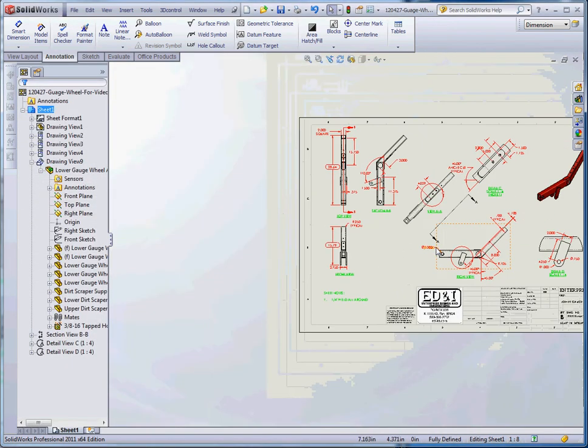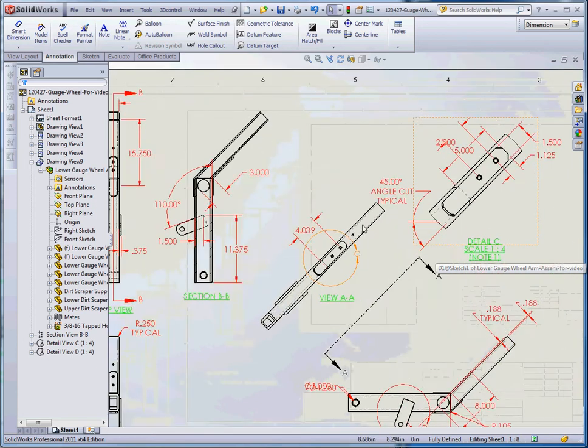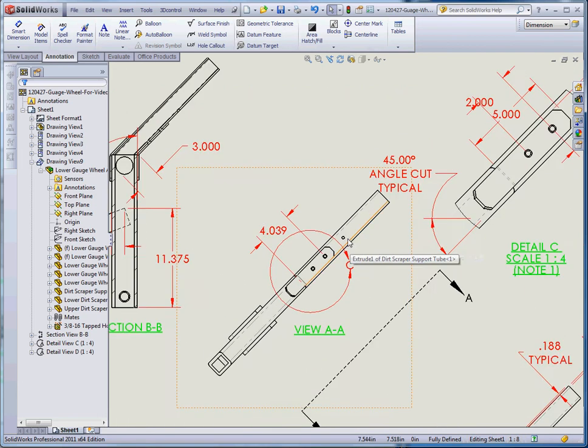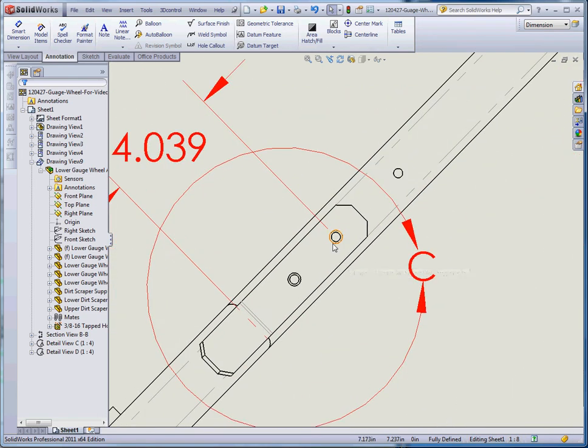And we'll go from there. Alright, so that's our height, length, and depth. Hole callout. It's difficult to get hole callouts on an assembly level. I'm sorry, let me back up. It's hard to get hole callouts on the assembly level when it's on the part level, but if you put a hole wizard location in on the assembly level, which you can, then it can call that out.